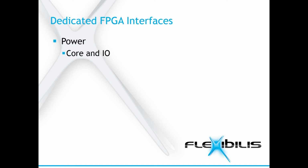FPGA chips have dedicated inputs for core and I/O operating voltages. The core voltages vary depending on the FPGA type, and the I/O voltages depend also on the I/O standards used in the design. The I/Os are divided into a few separate banks, and the I/Os in a bank share the same I/O voltage. The power consumption of the FPGA chip can be estimated with Altera tools.